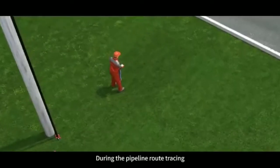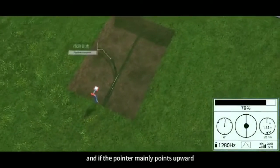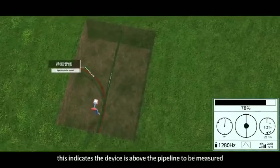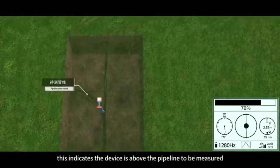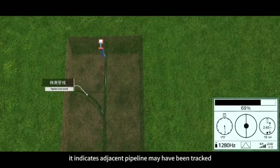During pipeline route tracing, observe the device phase dial, and if the pointer points straight upward, this indicates the device is above the pipeline to be measured. If the device displays a question mark, it indicates an interfering pipeline may have been tracked.